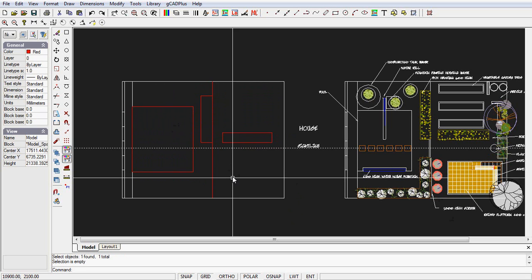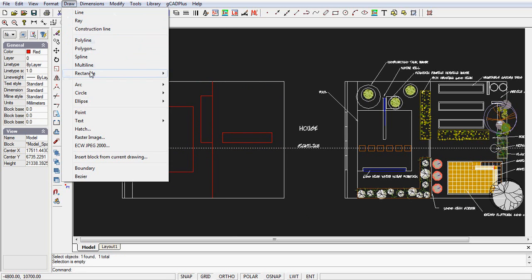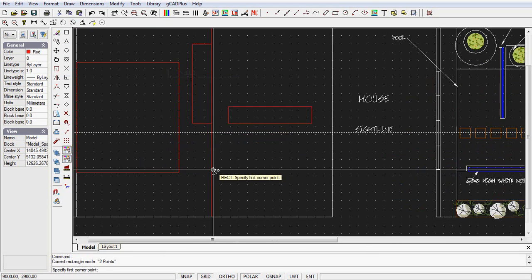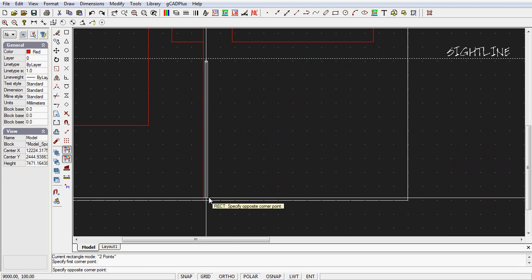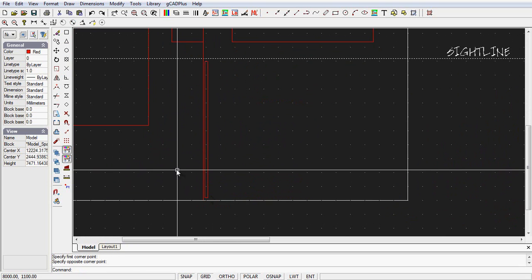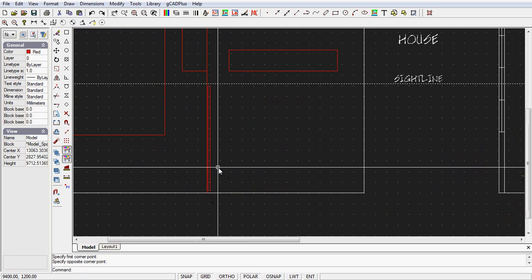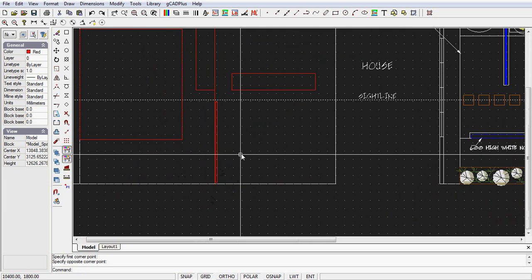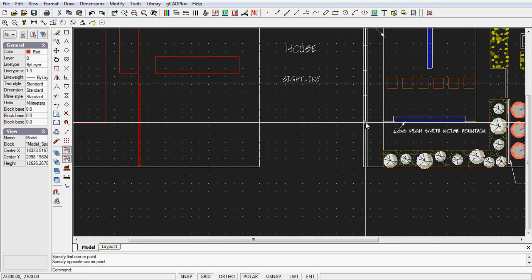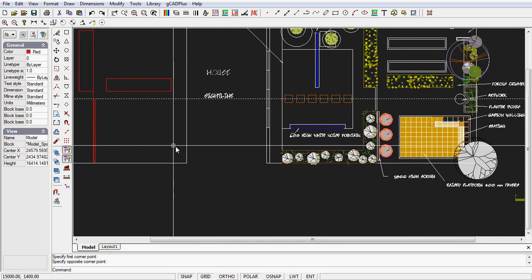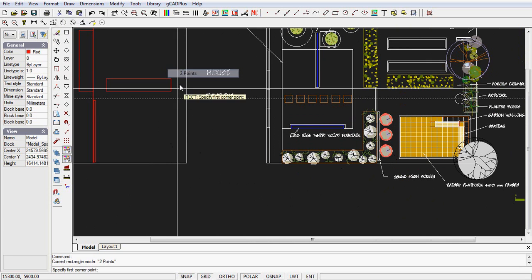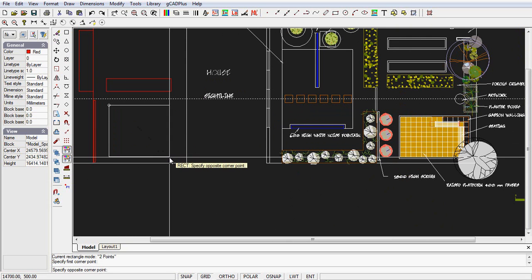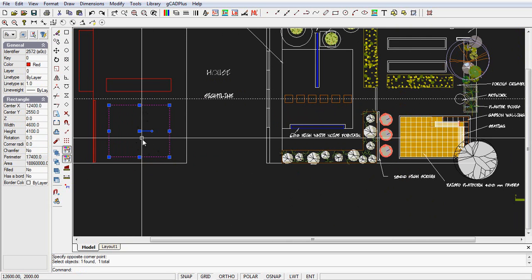If we wanted to put a screening wall through here, you could use again the rectangle and 2 points, zoom right in and just snap your rectangle in position. There it is, all done, and with measurements and distances it's very easy for a construction team to do. Putting in and designing some sort of slab is also easy. So it's another rectangle, and in it goes. Can you see that? Then I can move it around if I need to.